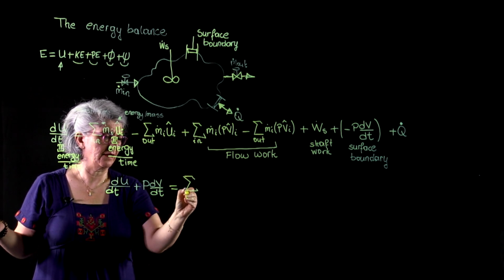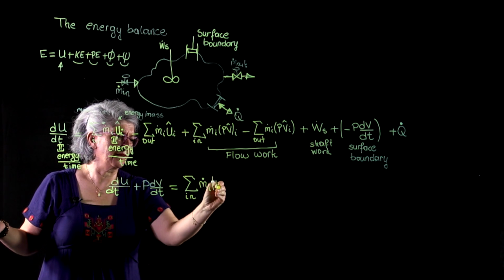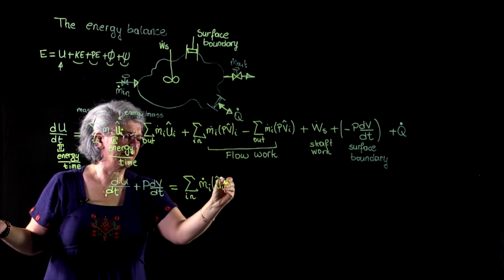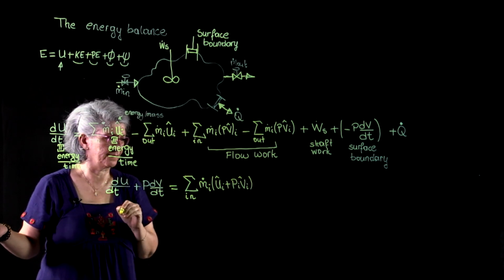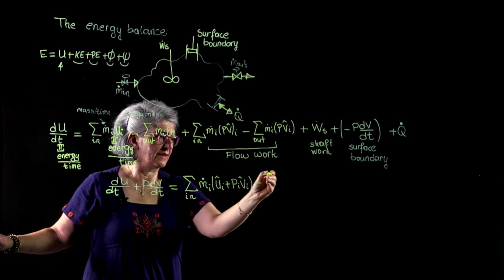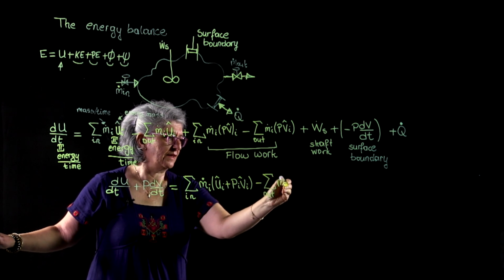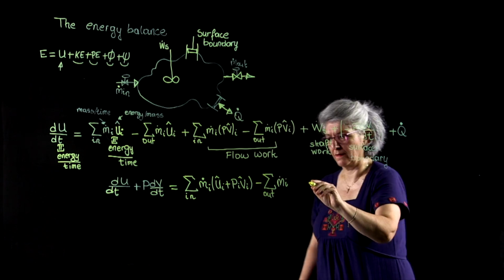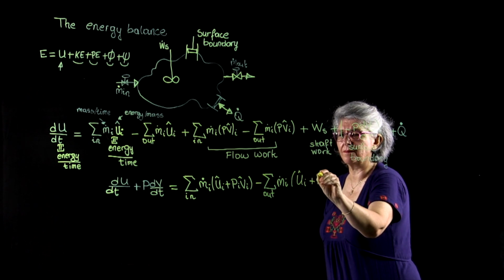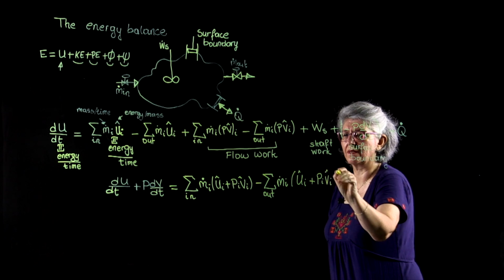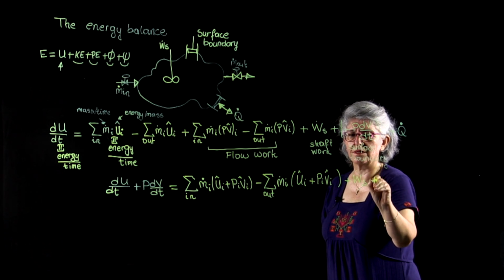summation of incoming streams with their mass flow rates, m dot i, u i plus P i V i, minus summation of outgoing streams, m dot i, u i plus P i V i, plus shaft work, plus Q dot.